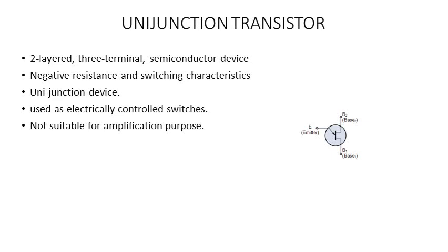A Schottky diode usually has almost zero diffusion capacitance and a smaller value of transition capacitance. These Schottky diodes are also called barrier diodes, low voltage diodes, or hot carrier diodes. Here, instead of P-type semiconductor, usually you fill it up with a metal. The metals will be mostly aluminum or platinum, and it does not have the capacity to store charge at the junction, because you don't have an N and a P together. It is not able to store the charges, because of the absence of this depletion layer.